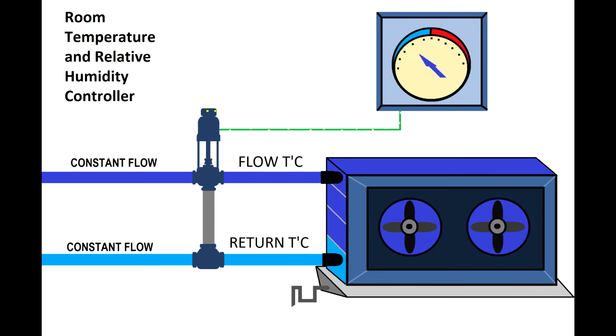See, this heat exchanger is running now, but if you look underneath at the drip tray, we're not removing moisture from the air yet because the coil might not be cold enough. So when you run a coil, a heat exchanger like this, you can run it a little bit warmer, just above the dew point, and then the air will be cool, but the air will not lose its moisture, its humidity.